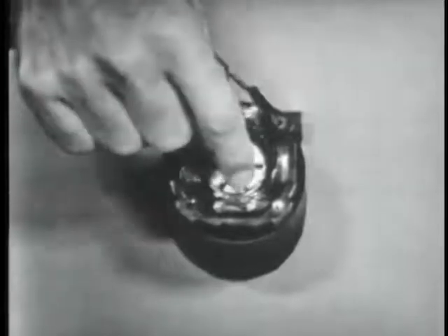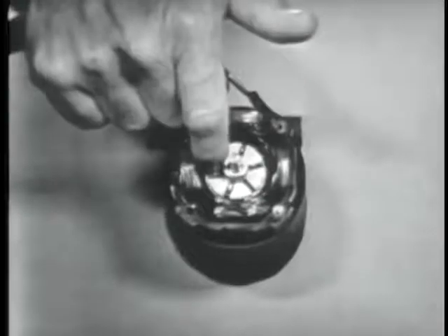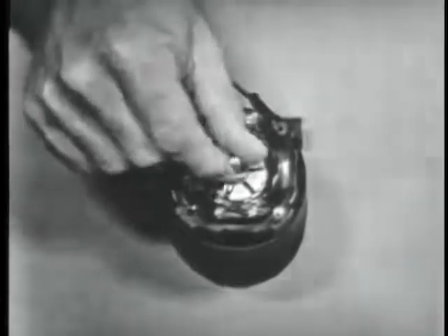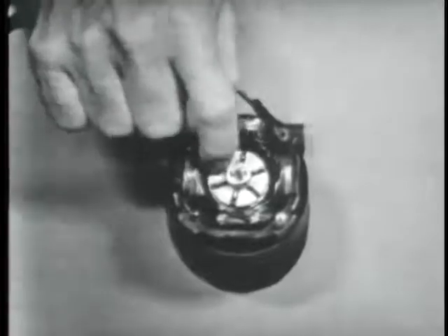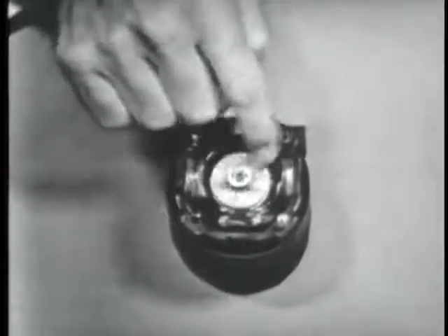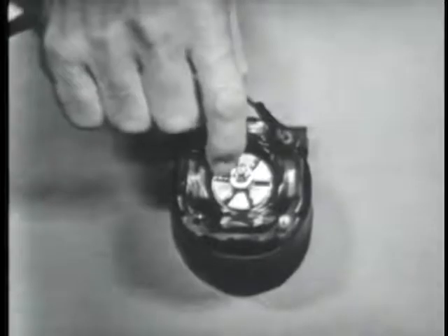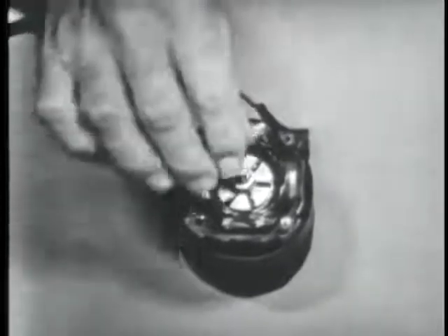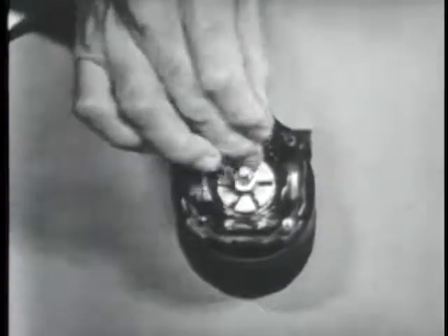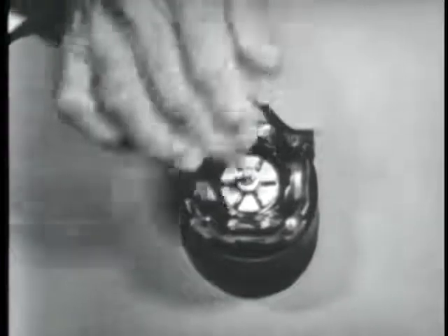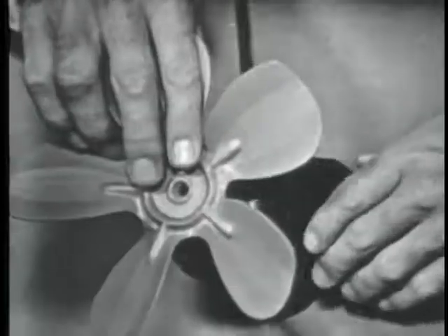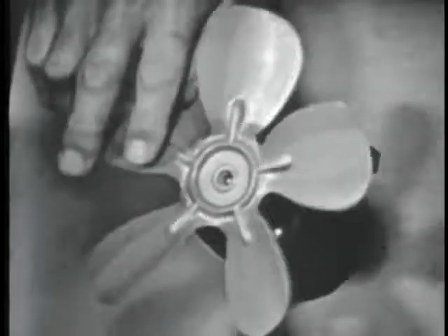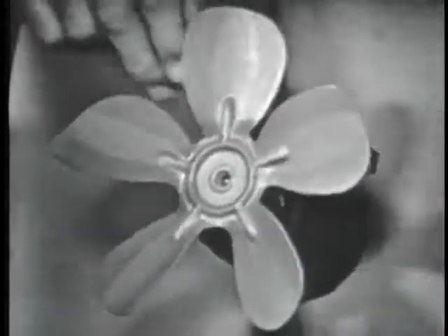Right. The same thing is true of this rotor. That is, it takes a certain amount of energy to overcome its weight to cause this hunk of iron to turn. And, of course, the friction of the rotor shaft on the bearings adds to the internal load. And there's a little cooling fan built into the rotor, and that increases the internal load. Now, the external load refers to the job or the work that the rotor must do. That is, turn gears or operate pulleys, or maybe turn a fan blade. That you just happen to have with you. Happen to have one in my pocket, right?